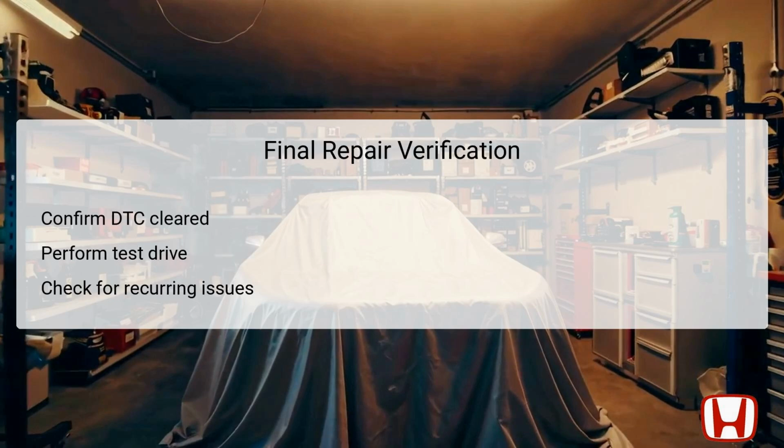After completing the repairs related to DTC P0102, it's essential to verify that all issues have been resolved. This involves making sure the DTC is cleared from the PCM using a scan tool. Conduct a test drive under various driving conditions to evaluate the performance of the vehicle. During the drive, observe if the check engine light remains off and if the engine operates smoothly without hesitation or